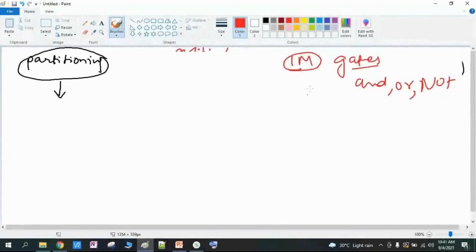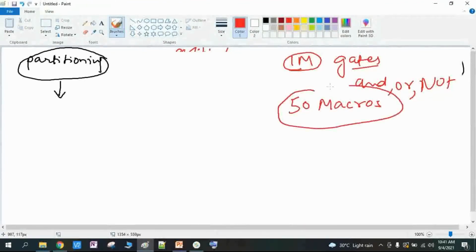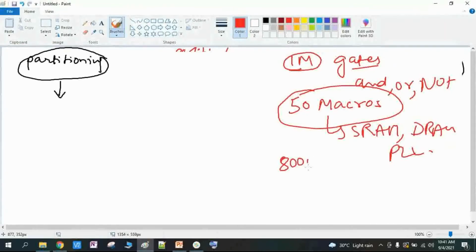Apart from that, he will tell that you have 50 macros. What are macros? That's what I was talking about right now: SRAM, DRAM, PLL, all those things, big modules. Clear enough? Is it clear till here? Yes, sir. And he will tell that you can use a height and width of 800 micron by 720 micron or 750 micron. This is the dimension he's giving.